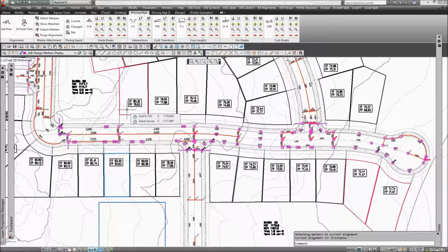variable height curb definitions, and a few others, true lengths on grades, and most anything you'd need for pretty much any municipality. So we'll start out by defining grade breaks first. Those are the one feature that is a requirement to generate a finished ground profile. So we'll need profiles for each component of the profile. So I'll just start with center lines.